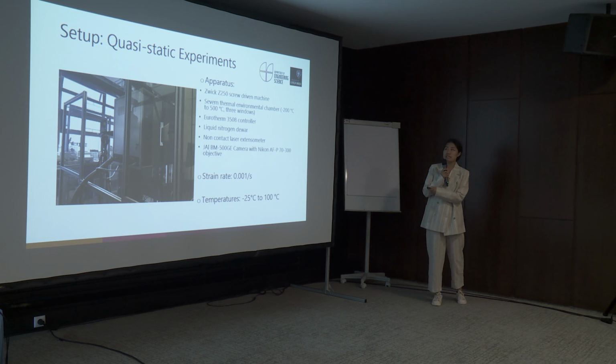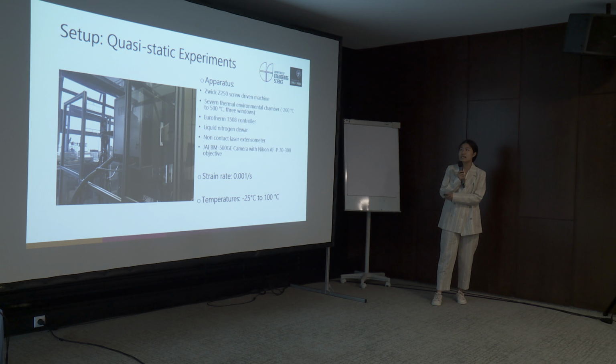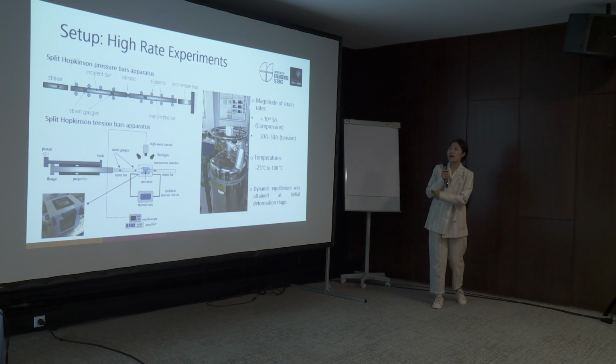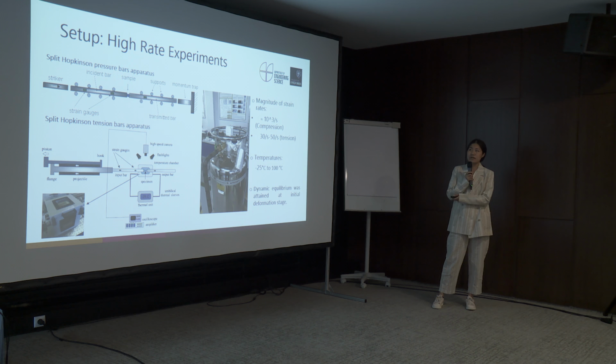The quasi-static experimental apparatus, including the following equipment, was operated at a strain rate of 0.001 per second. The split Hopkinson pressure bar apparatus and the split Hopkinson tensile bar apparatus were used for the high rate compression and tension characterization, respectively.